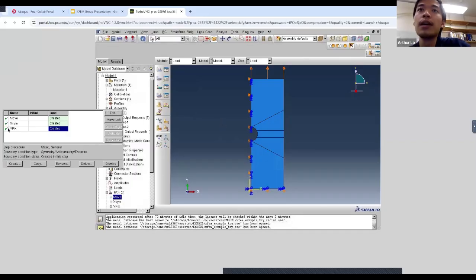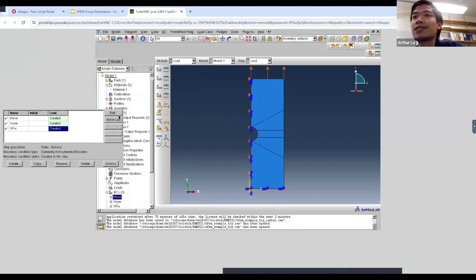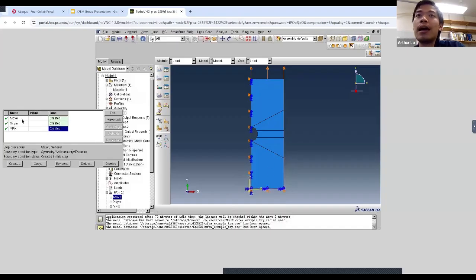We can do it over here, actually. So I imposed two boundary conditions and one displacement condition, essentially. You can see, for example, over here, I defined that this edge could not move in the x direction. It can move in the y direction in response to displacement, but it can't move in the x direction. Similarly, I fixed the bottom of the model to be unable to move in the y direction so that it's fixed even though we're trying to pull it upwards.